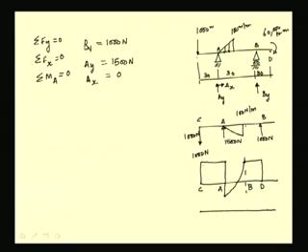The area under this curve in this portion CA constantly increases, and the bending moment is negative of the area under the shear force curve. So it has to be linearly increasing, and then for this portion it is a little more difficult to directly determine. So let us consider the portion BD.